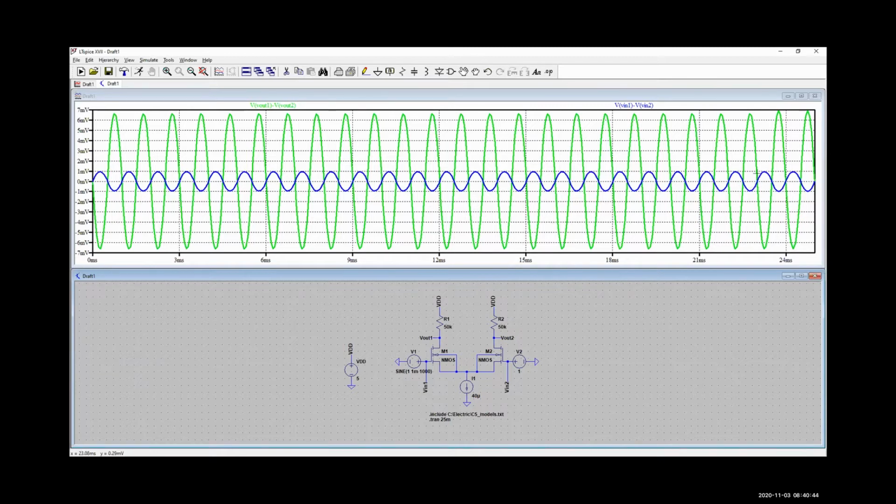Our input signal is well behaved. I'm not sure why the last cycle or two is showing a gain of almost exactly 7, because after 25 oscillations, I would figure that this would be behaving as effectively sinusoidal steady state, but it doesn't quite appear to be. So, all right, we have a differential gain, V out divided by V in, of approximately -7. So let's talk about why this happens.